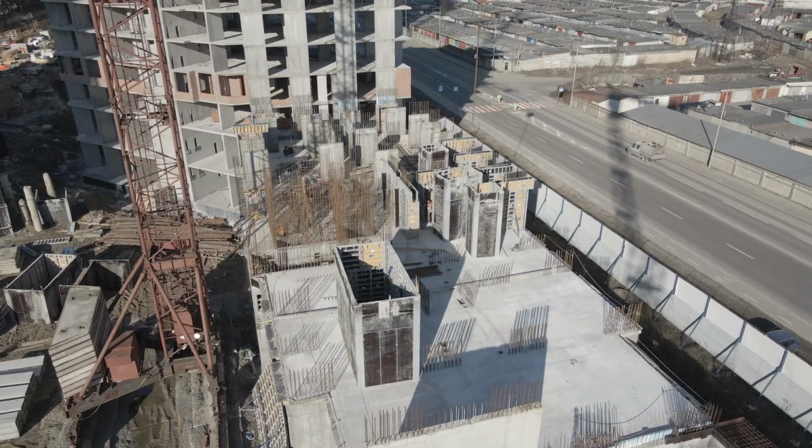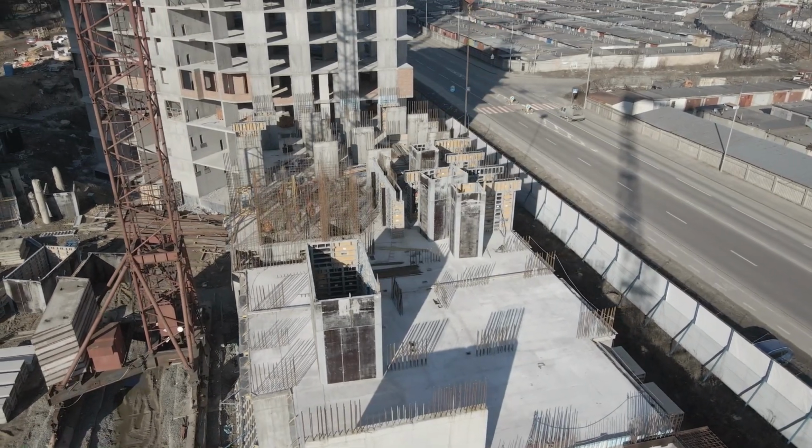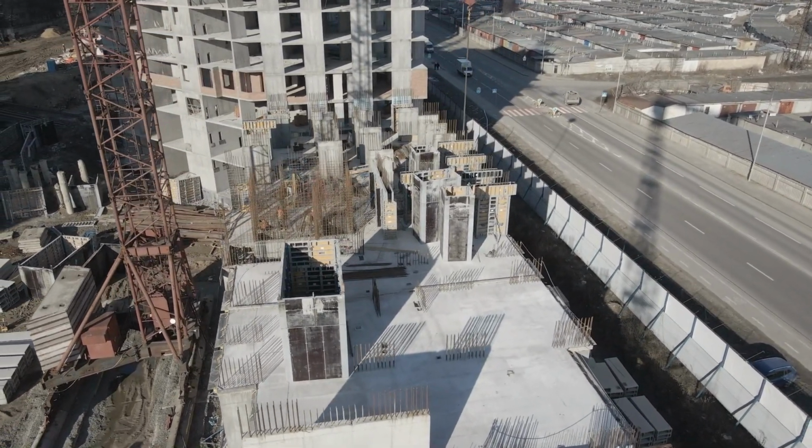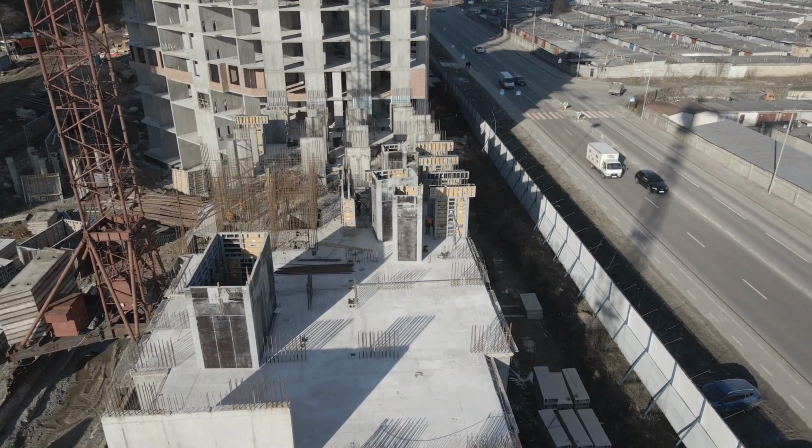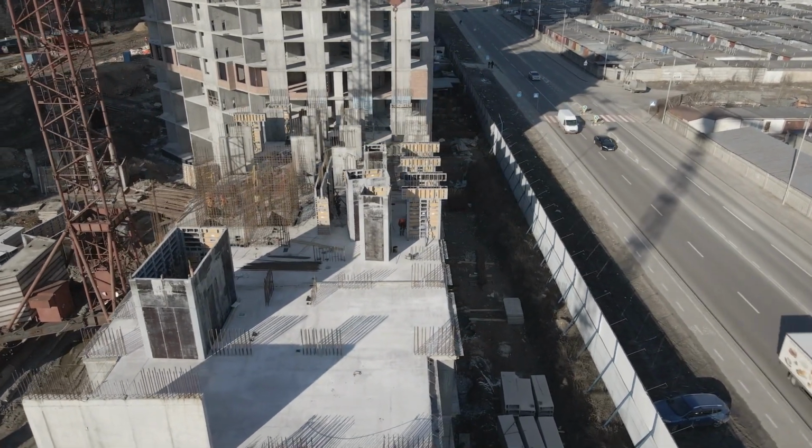The design and construction of formwork must consider both safety and the required surface finish. The formwork must be rigid and tight enough to prevent cement slurry loss from fresh concrete or the formation of fins and honeycombing on the surface.